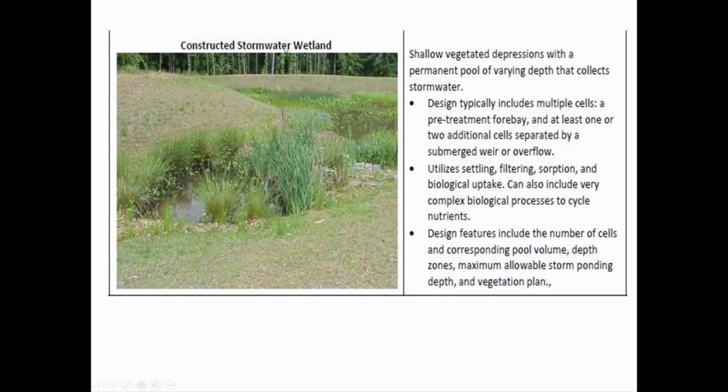A constructed wetland is becoming quite popular because constructed wetlands have a way of improving the water quality. Constructed wetlands are like a stormwater pond that's meant to always have some water in it. We'll look at some sketches, some hydraulic sketches of the types of fittings you'd need for an extended aeration basin versus a constructed wetland and so on.